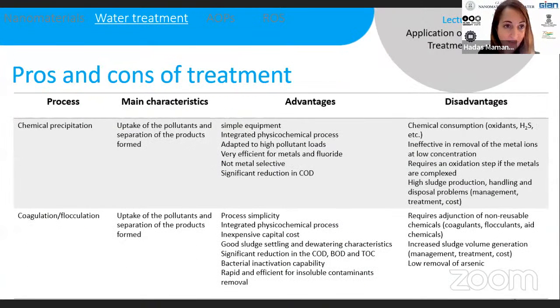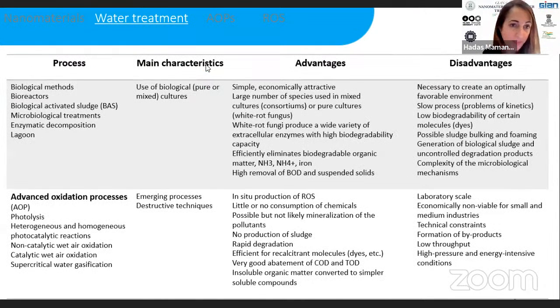them very soon. Okay. Now, we'll go over this really quickly because we already discussed these issues. But if we compare biological treatment versus advanced oxidation processes, they're not actually competing, because usually AOP in wastewater will come after biological treatment.